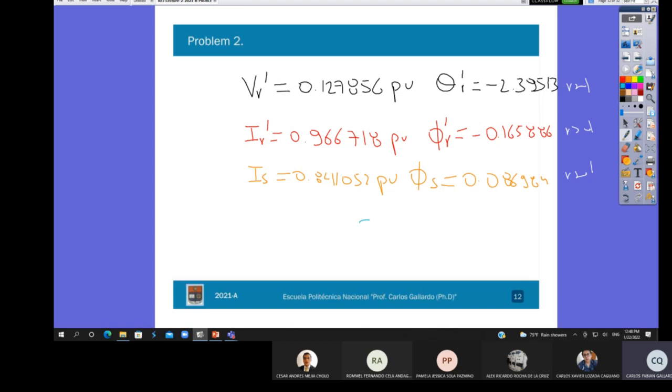Solving the 7 by 7 equation, the slip is equal to 0.099857 per unit. This is the solution of the single-phase equivalent circuit model of the Doubly-Fed induction generator. This is my first step.